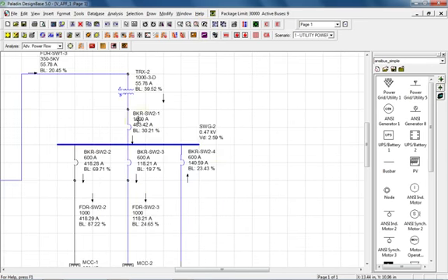For instance, selecting the output results to digital meters allows you to very quickly navigate the results of the study using different types of gauges and outputs that provide great visual impact. It also allows you to filter results based on voltage and current violations. This interface is very handy if you're doing a presentation to an audience and don't want to scroll up and down through a lengthy text report.